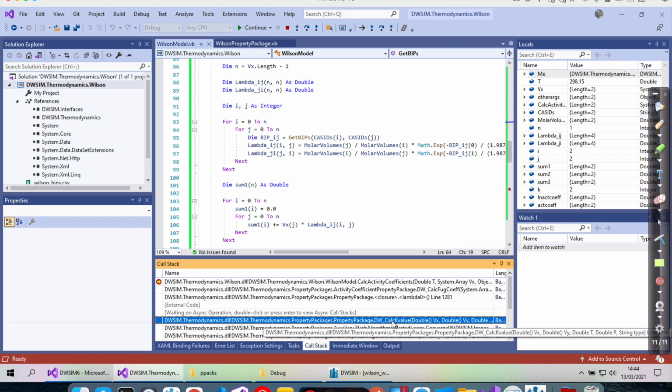Is there a way that you can actually bypass all this step and force the phase to be something that you decide at the very beginning? In many cases, I'm not talking about the particular case that we were discussing before. But just for example, when you have a separator and you are using plant data, any deviation, this means you have a set of pressure and temperature, and you can be 50% of the time as vapor when actually you are liquid, and the opposite. I don't know if you get my idea.